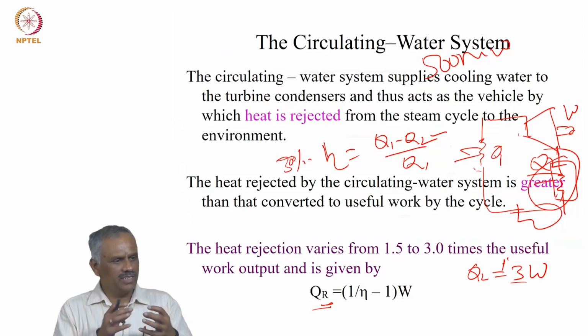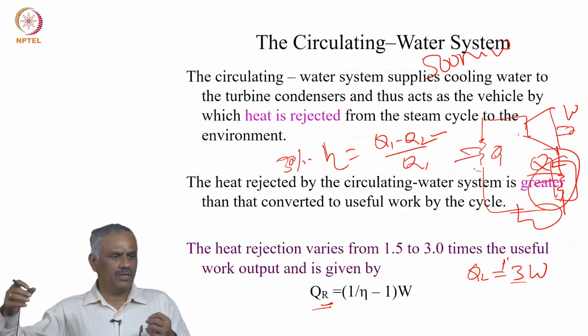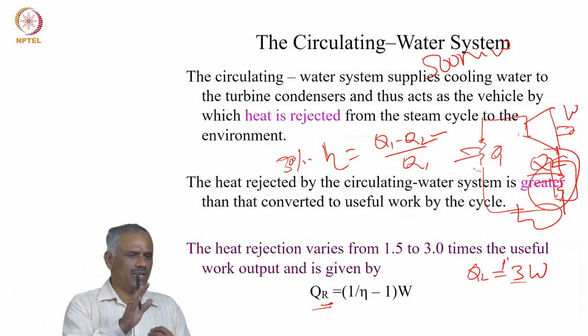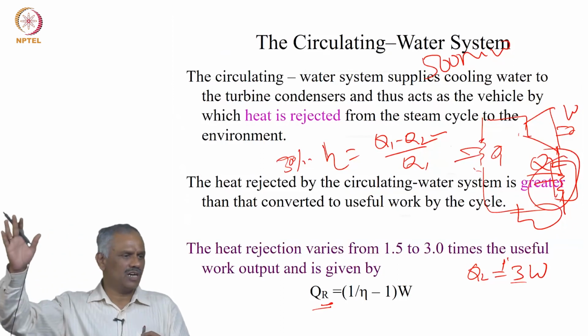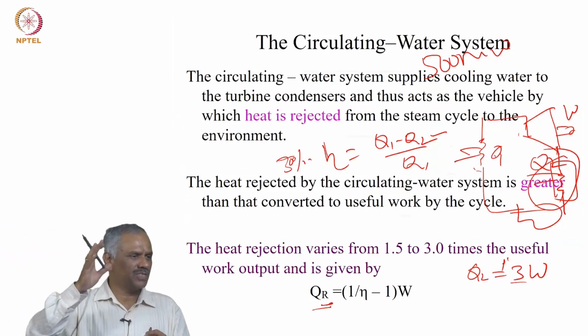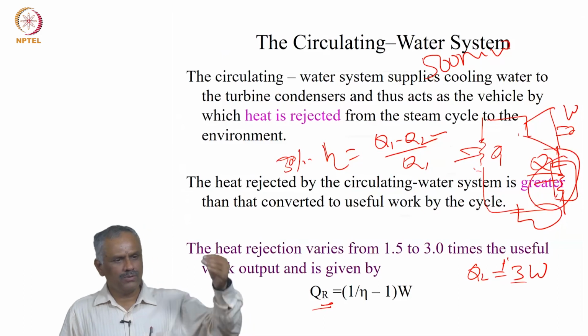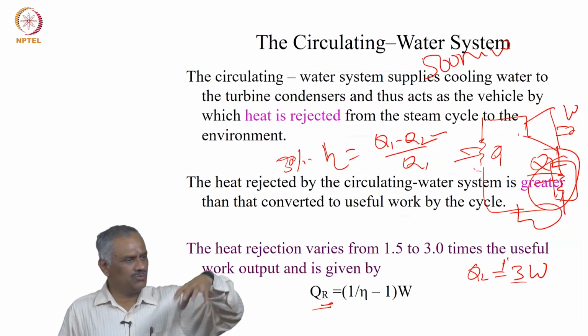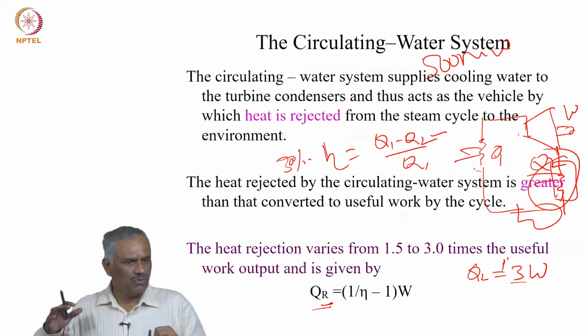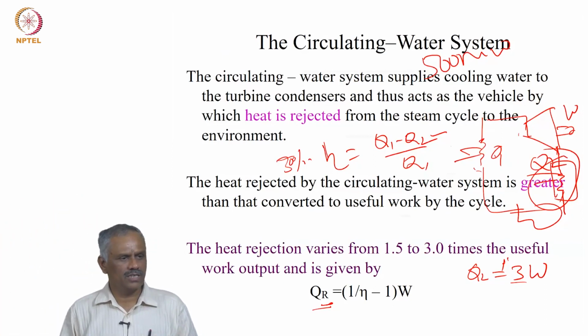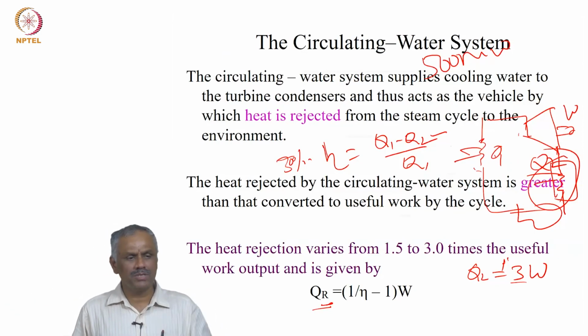But then this heat you have to take out, then use again design a heat exchanger, that is a condenser, where you supply cold water and remove this once it picks up the heat and you send out. And if you, for example, send 1 kg of steam you need to condense, you have to spend a large number of water to recover this heat at low temperature. It is m C_p delta T, that is all.